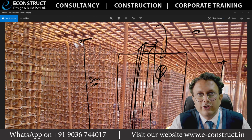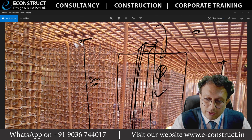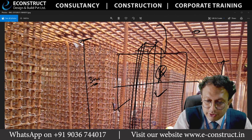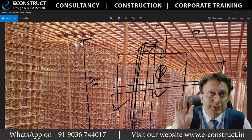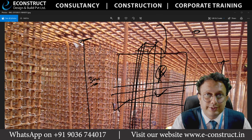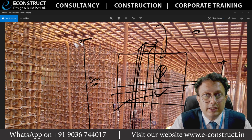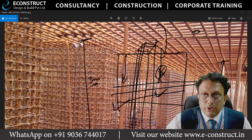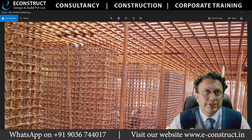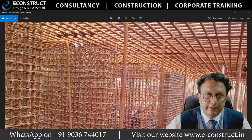So in this kind of context, I just wanted to tell you very surely that you need to design this also. Or sometimes here also you require to give the bracing, because it should not buckle anyway. The bracing in this direction, bracing in the other direction, because that is also a column, right? Steel column, rebar column, but a column. Why? Because it is taking the compression force. Understood? So how to design the foundation system is what we are talking about, and how the work is happening.